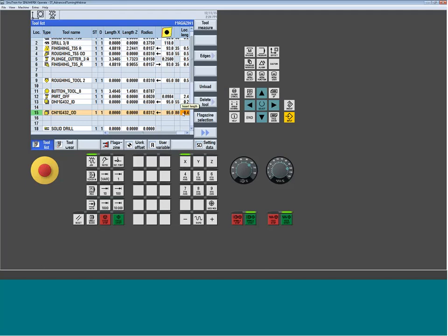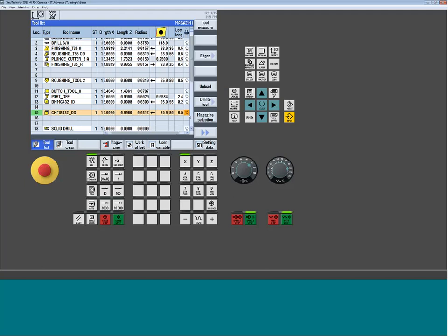And then the final question was the IC diameter. Remember, that's that inscribed circle. That goes off of the 4, which in this case, according to our chart, was a 1/2 inch. And now I have enough information to know where the tool is and kind of how it tracks and how it goes.